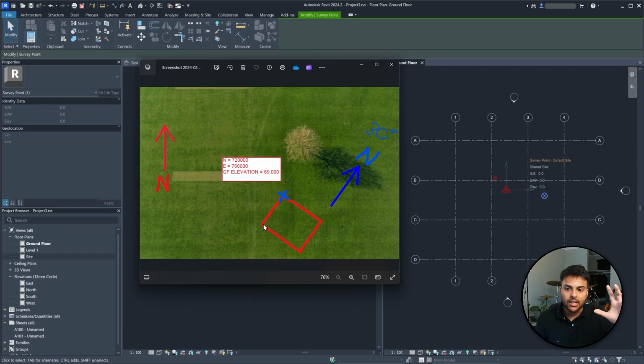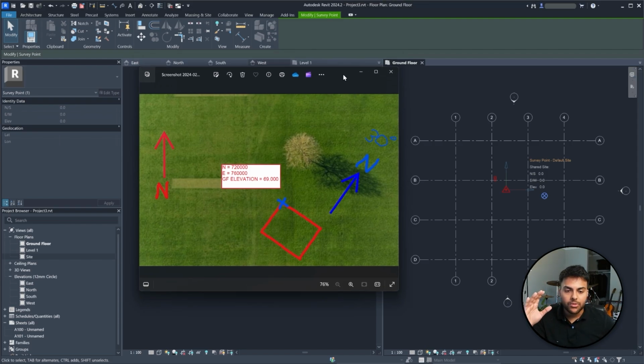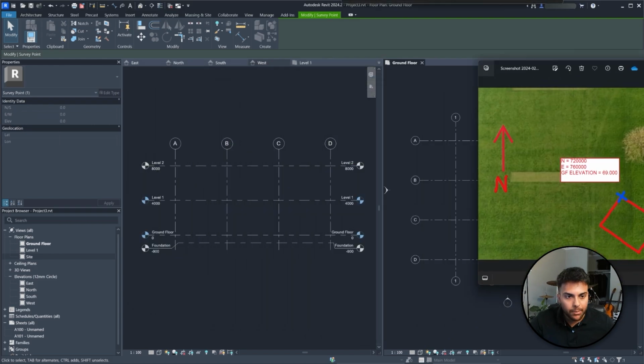The general idea is you want to make it so it's easy to explain and less likely to change later on, right? Generally, what we try to do is set it up to the top of the ground floor slab, in an area which is not likely to move. So the intersection of two grids is very likely to be where it's going to be set up. So for now, let's set it up similar to this.